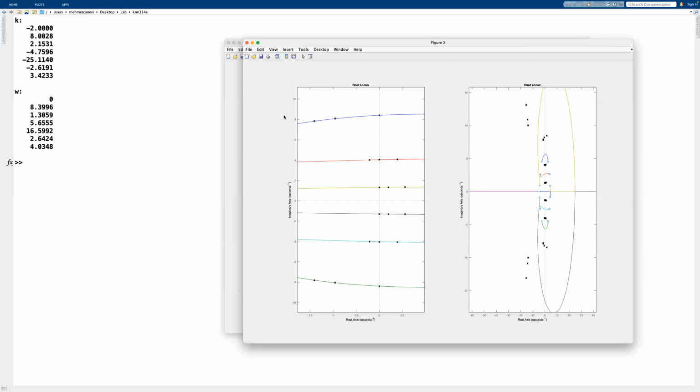Once we're done with that, what we have to do is actually convert this back into the real world. So when you use the Laplace transform, let's say you want to calculate the step response of a certain system. What you do is you convert the system into its transfer function representation in the Laplace domain. You solve that problem in the Laplace domain, and then you take the inverse of that, which is basically you go back to the real-time world and check if it's correct or not.